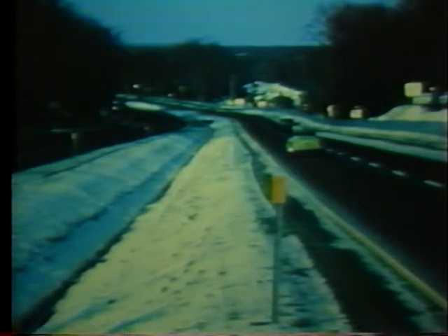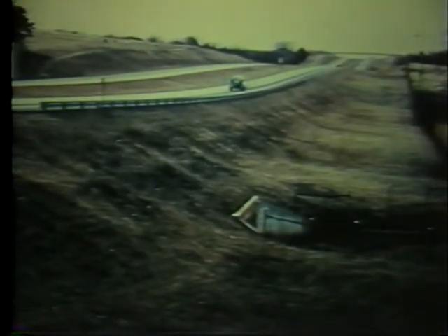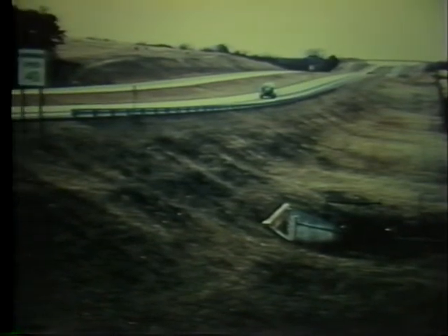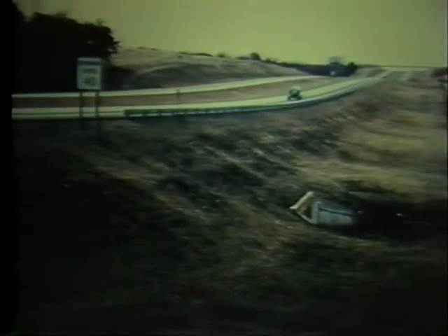Rigid obstacles on slopes or in the ditch region, like you see here, can destroy the safety features of an otherwise traversable roadside. The primary hazards found on slopes alongside the roadway include sign supports, luminaire supports, curbs, and drainage inlets. So it isn't enough to give attention to the steepness of the slopes and the cross-sections of the ditch. The expected path of vehicles that leave the road also needs careful attention to be sure it's clear of rigid objects.